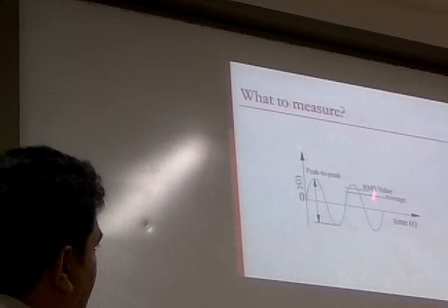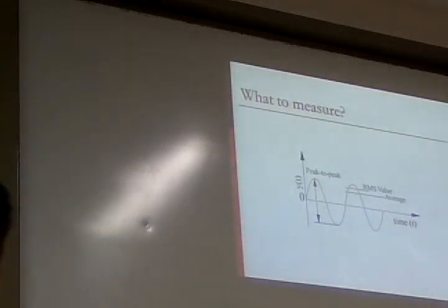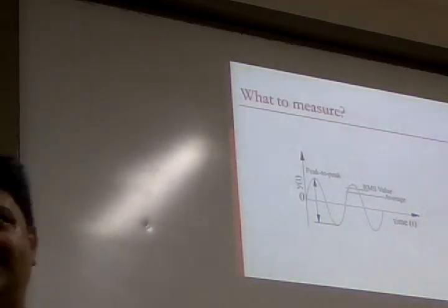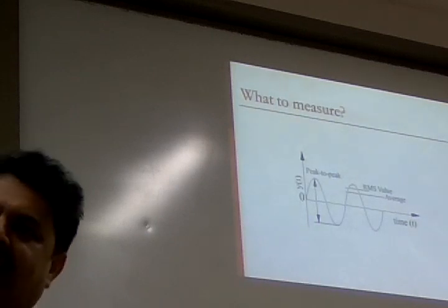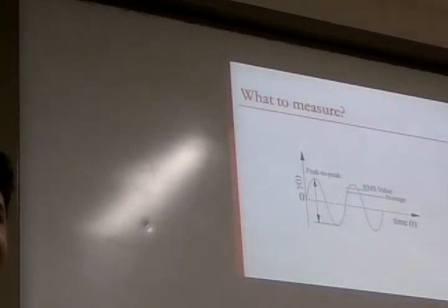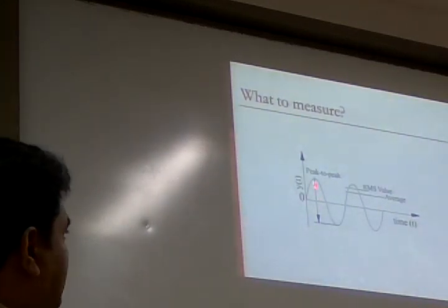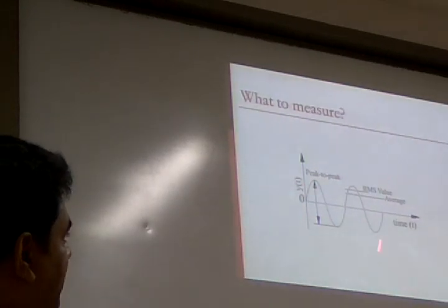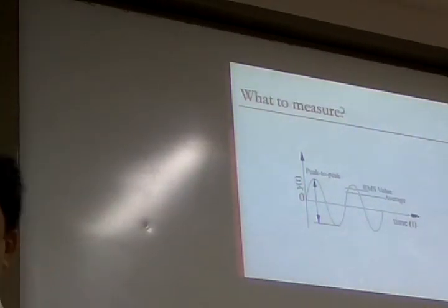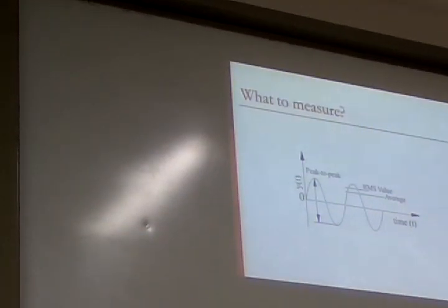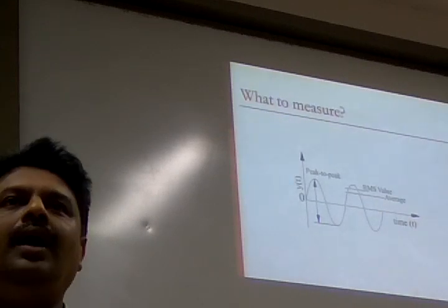With respect to time, the scale moves up and down, or this rotates clockwise and anti-clockwise. So with respect to time, the theta changes in case of angular displacement. In case of scale, the displacement changes. Y of t changes with respect to time, sinusoidally or in some fashion. It need not be a perfect sine wave all the time. It can be a zigzag waveform also, but it is a waveform.